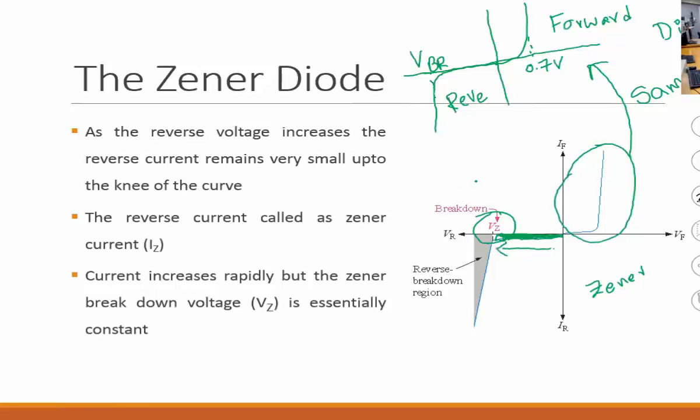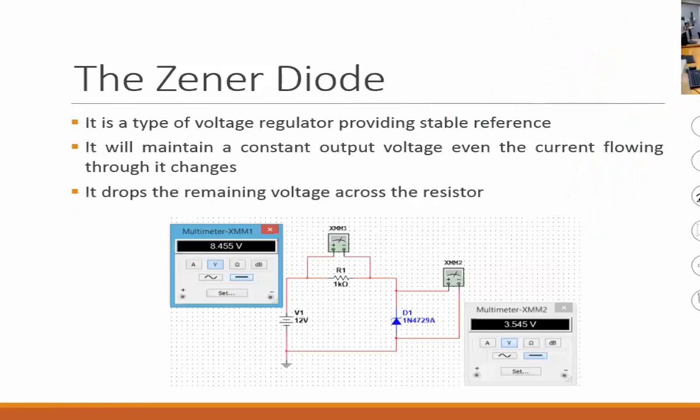you will hit a voltage where the Zener breakdown occurs. That could be 3 volts, 4 volts, 10 volts, 20 volts, 400 volts, whatever the model of the Zener diode is. But when you hit that VZ, the Zener will allow the current completely under this reverse condition. But you must hit that VZ. So let me show it to you.